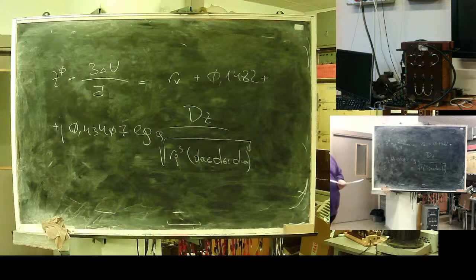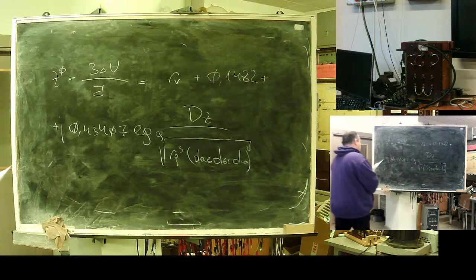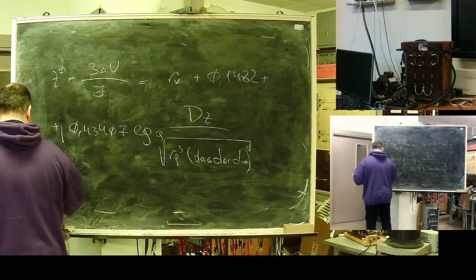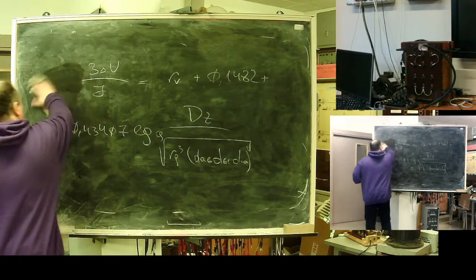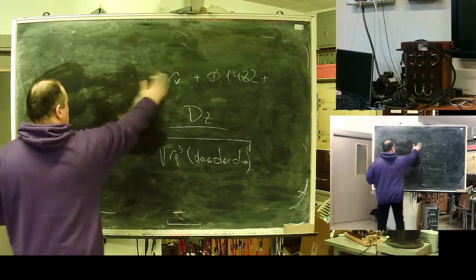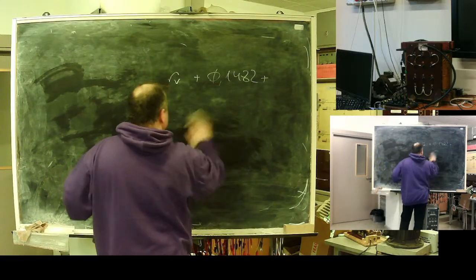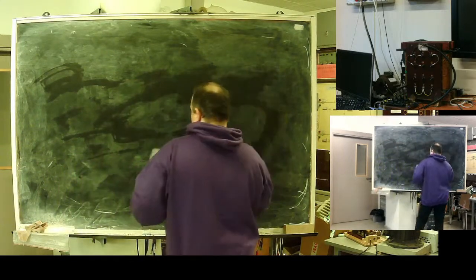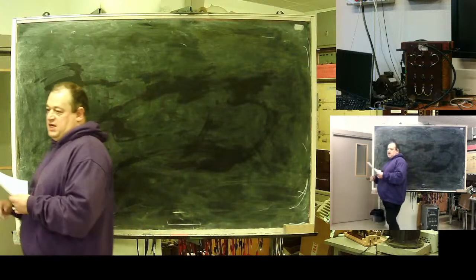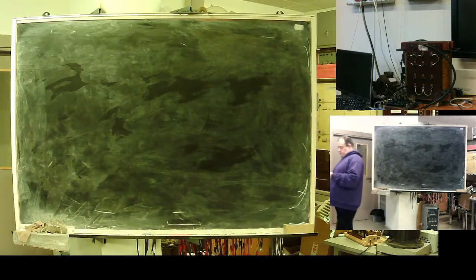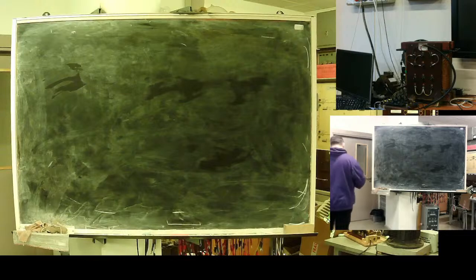But this formula is true for small betas and for fully transposed lines. This formula assumes line symmetry. It's okay for faults, but when we speak of high precision fault location, this formula does not work.